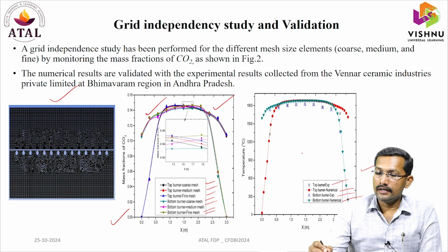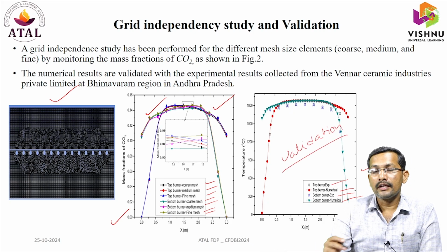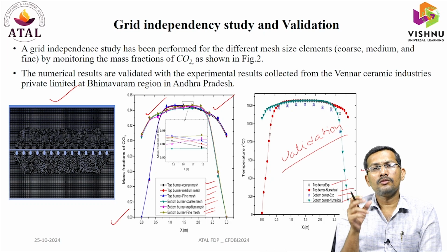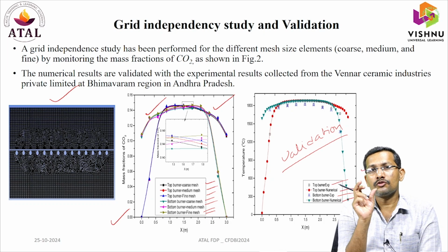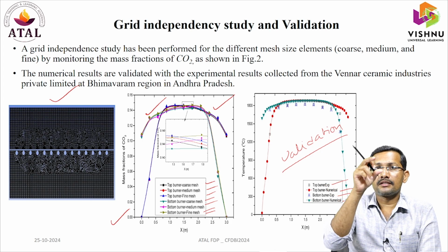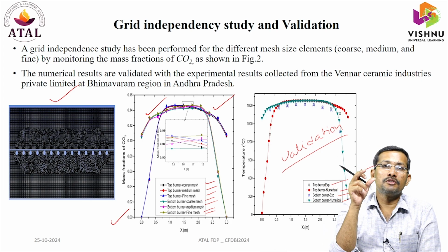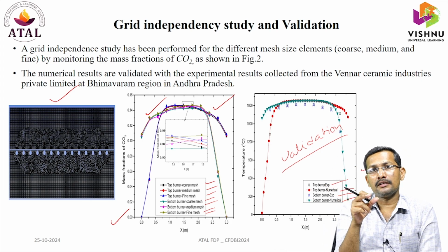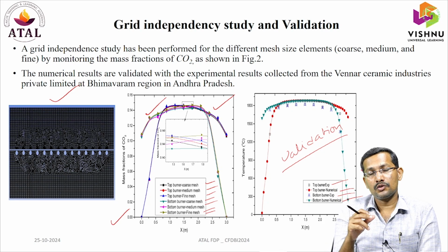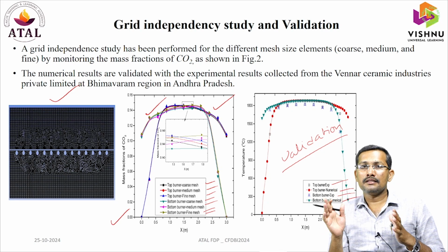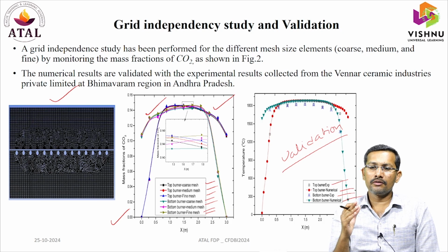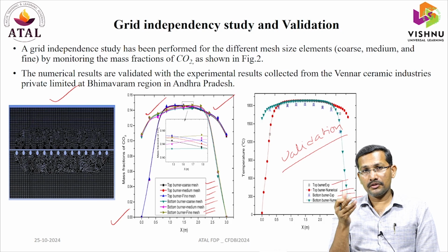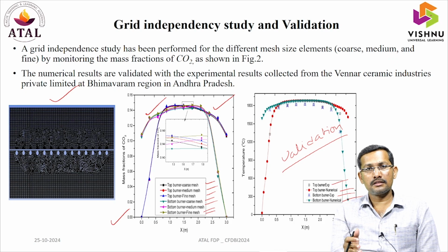Okay, what does validation mean? Validation is nothing but this: for any numerical solver, for any numerical problem, if you are getting some numerical results, they will be compared with either previously investigated experimental results, or maybe some theoretical results, to see how much deviation there is. If there is very little variation, then we can proceed with the numerical methodology which we followed for getting these results.